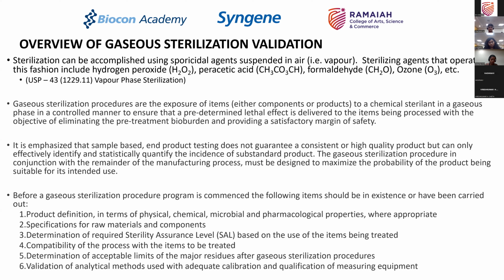Okay. Now, gaseous sterilization procedures are the exposure of items to a chemical sterilant in a gaseous phase in a controlled manner to ensure that a predetermined lethal effect is delivered to the items being processed, with the objective of eliminating pre-treatment bioburden and providing satisfactory margin of safety.